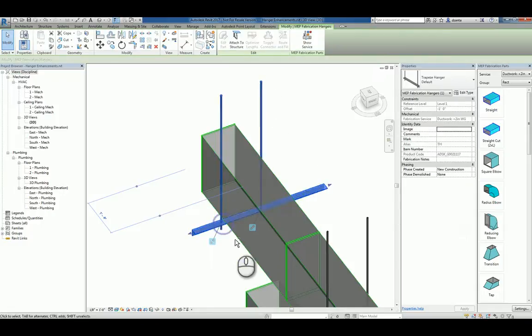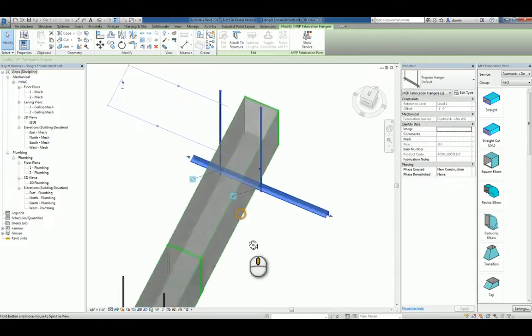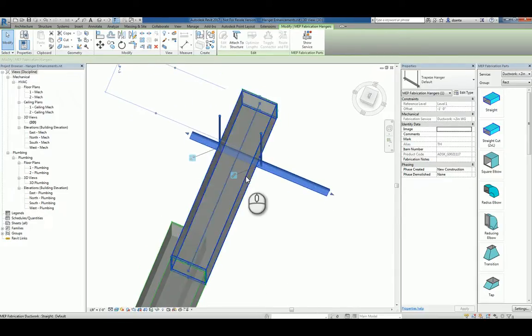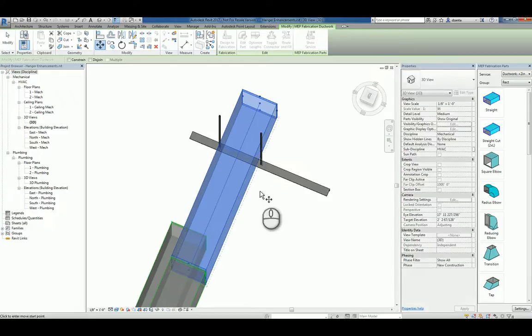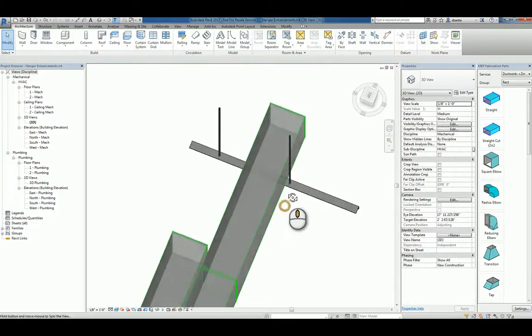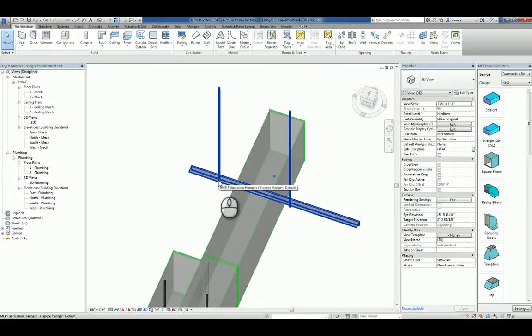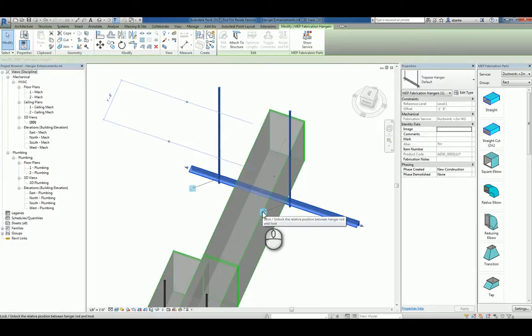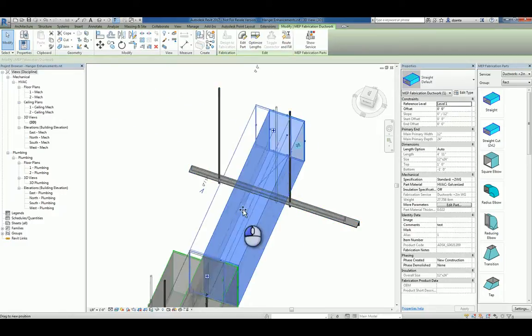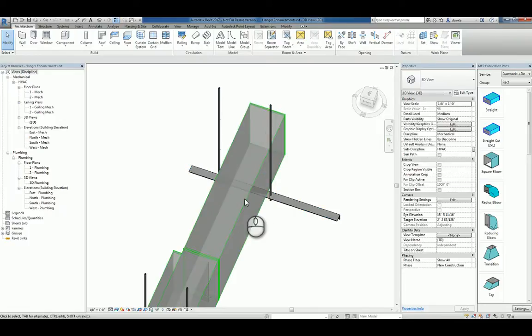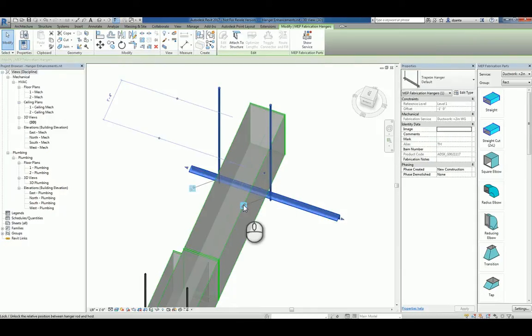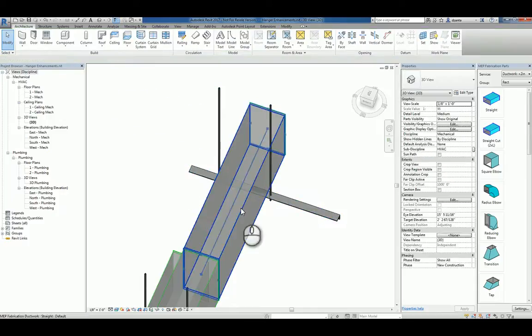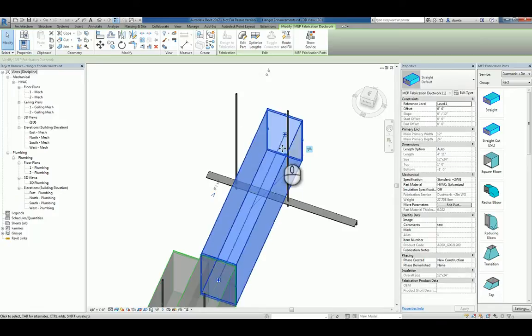And then if I move the duct to my right or left, you'll notice that this particular rod, since it was unlocked, doesn't hold a relationship to this duct. It stays put, and now the gap is here. Whereas this one, it actually is locked. So if I move this duct back, this particular rod stays in relationship to this duct. So that's what this lock and unlock feature does. And so if I lock this again and I move the duct, you'll notice both rods will move because both are connected.